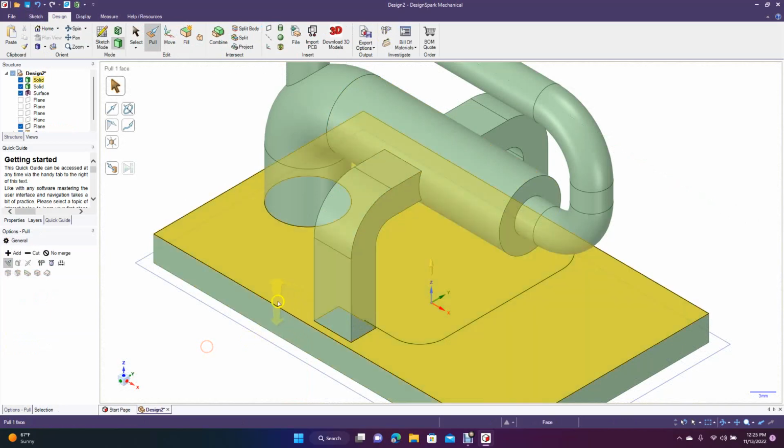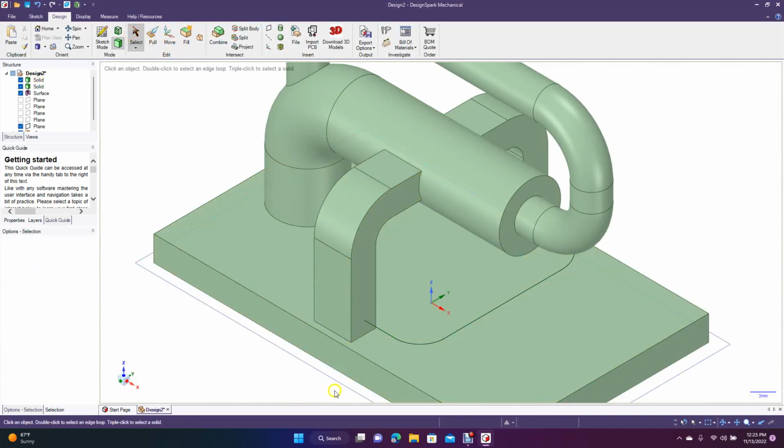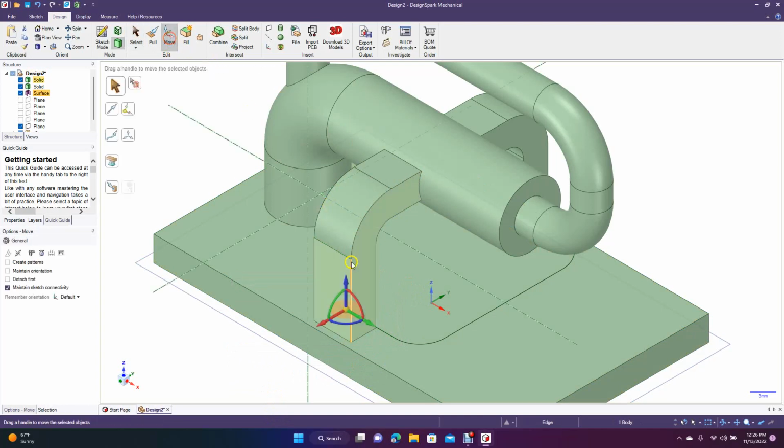The circle is on the inside there, so we're going to have to select the click off, and let's try to grab it. There it is. All right, so let's go to move, and we're going to grab the red there, and we're going to rotate it 90. So hit 90 like that. And now we need to move this forward a little bit, right to there.